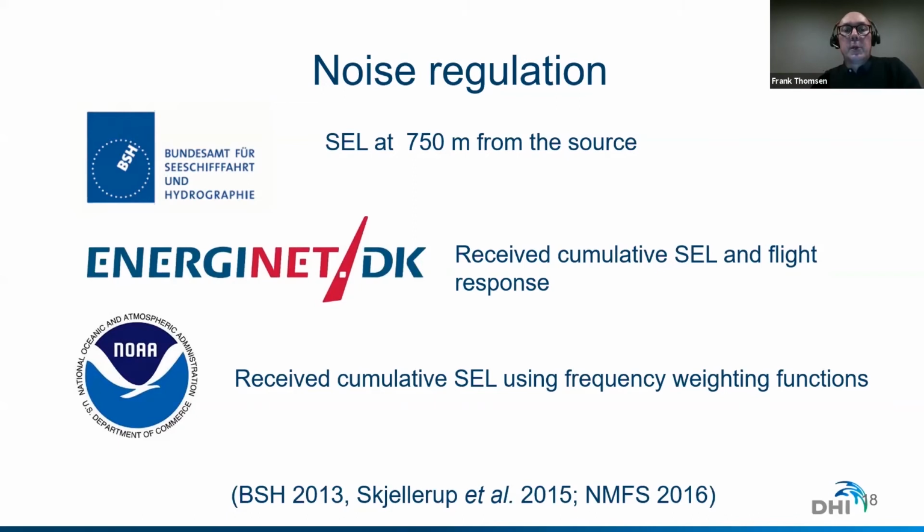You just have to put an underwater microphone at 750 meters distance from a pile driver in this case, because in Germany pile driving is a big issue, and then measure. And if the threshold is exceeded, the activity has to stop. In Denmark, Energinet has defined criteria based on received cumulative sound exposure level and flight response.